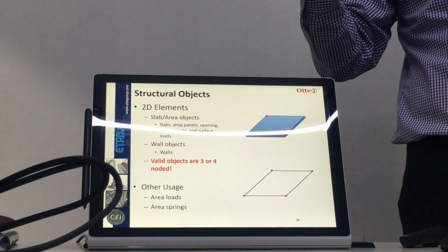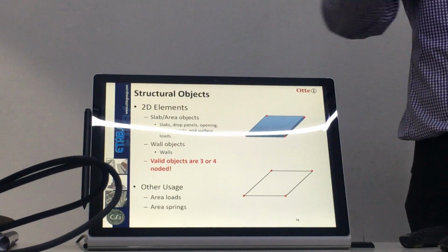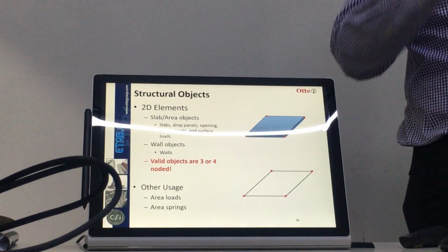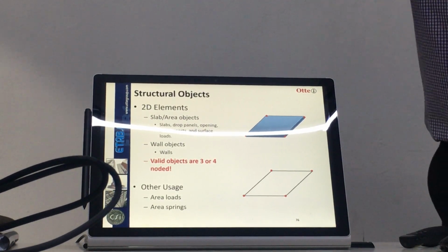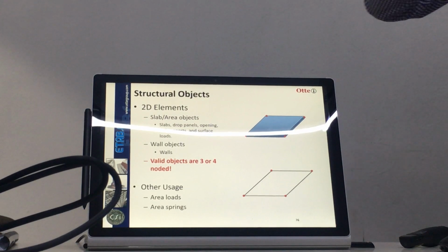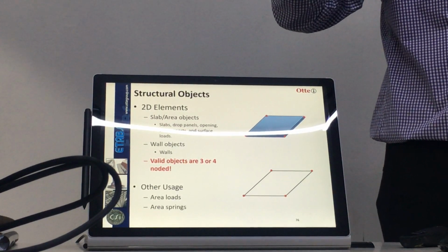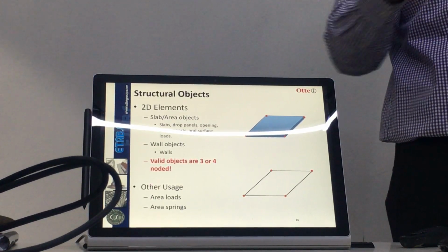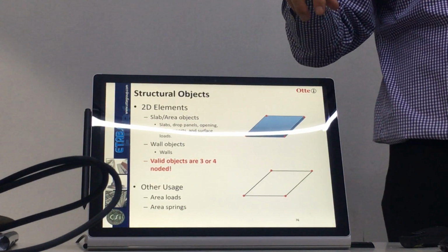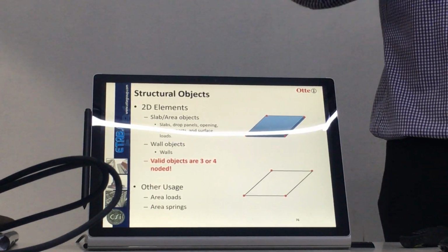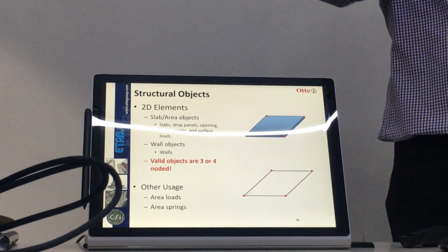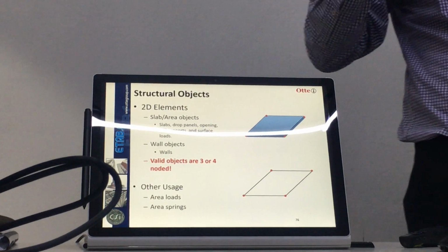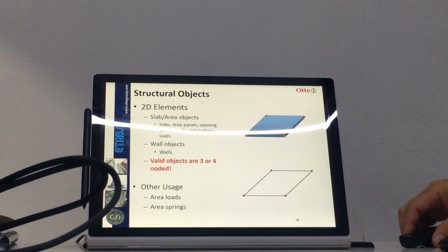I only have 5 pieces, and then Etabs will go in and look at these 5 pieces, and mesh for you accordingly. That's what Etabs does. So compare the 5 pieces to the finer pieces that you draw small piece by small piece, right? If Etabs applies the routine to check every slab before it analyzes the mesh for you, it will take a lot of time to check all these things, right? Even though after it checks that nothing needs to be done, it moves to the next slab. So it's not advisable for you to draw many small pieces. Instead, always remember, you draw floor based on usage, because of loading, and based on property. Okay, that is the key concept. All right.